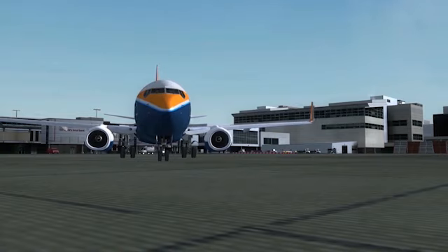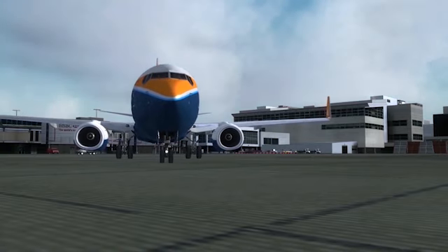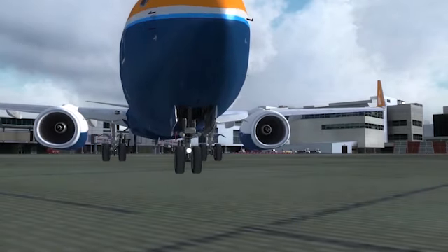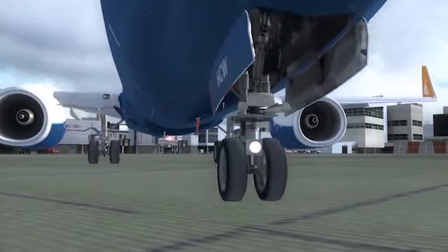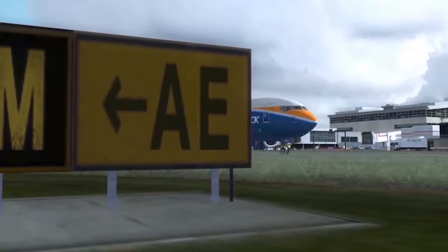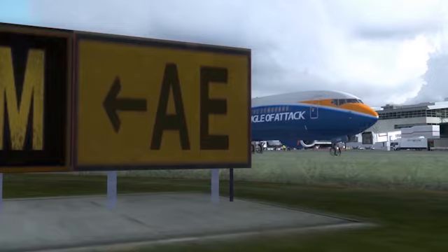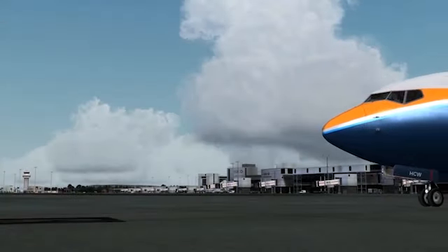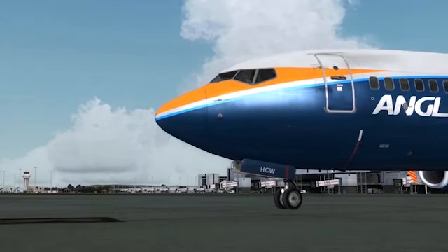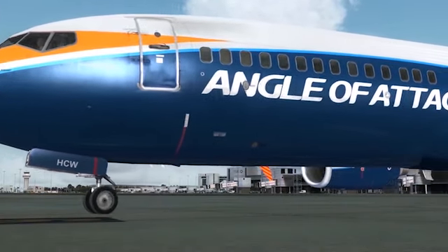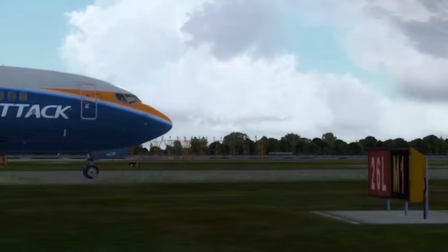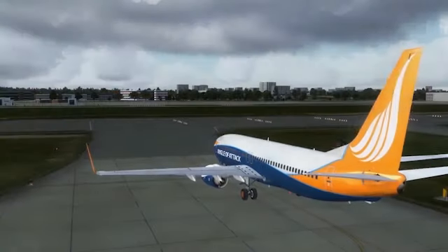The air conditioning packs supply cool conditioned air at one specific temperature that's in accordance with the coldest of the 3 cabin zones. Because of this, the other 2 cabin zones may end up being colder than they need to be. To counter this condition, the other 2 cabin zones are precisely fed with warmer air to bring the zone air temperature up to the desired limit. This warm air is known as trim air. We'll talk about all these systems and components progressively, so let's start with the air conditioning distribution system.